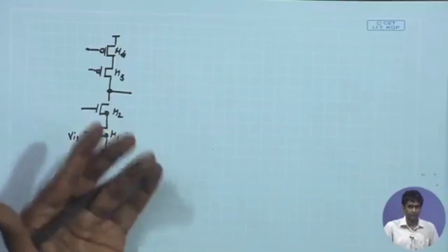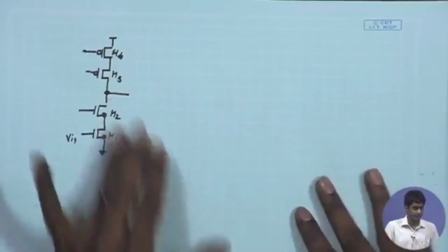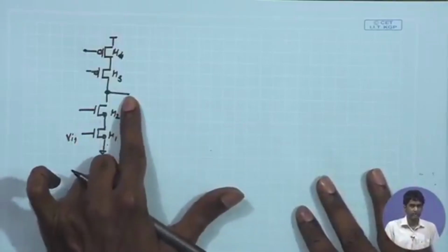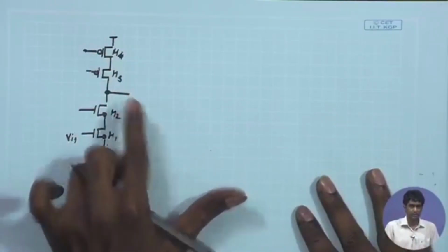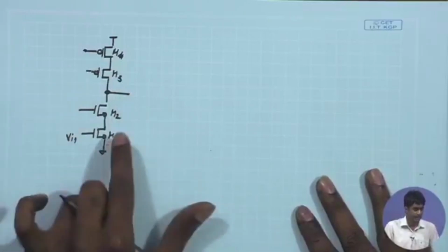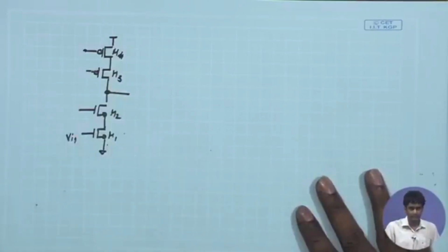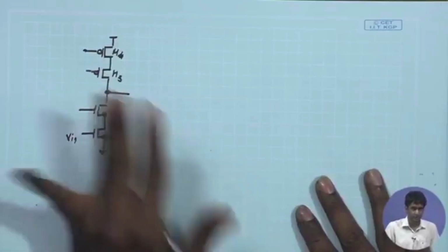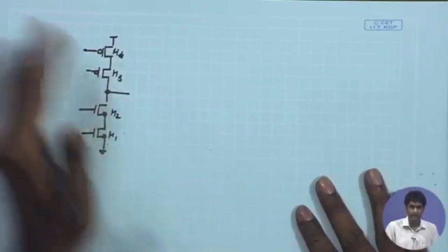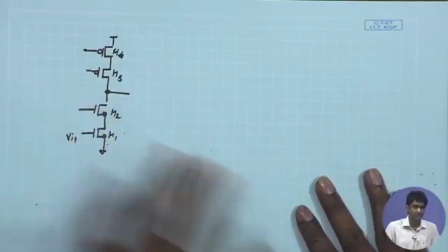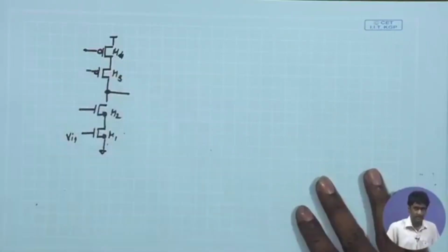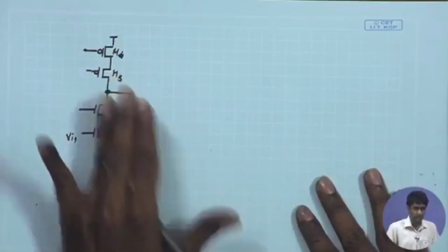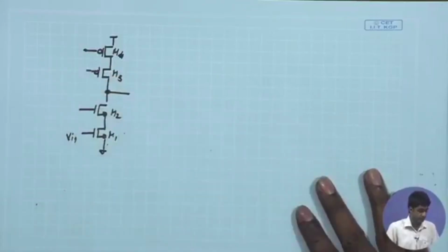And therefore, if I have to compensate the closed loop operation involving such amplifiers, I would like to just compensate this dominant pole. I would like to just push it towards further lower frequency and obtain an overall phase margin of 45 degree. So that is one of the advantages of this stage. You are having self compensation. One of the poles is already dominant and you want to just push it by another significant factor so that it goes down. You are getting a larger gain. The overall gain is comparable to the two-stage.